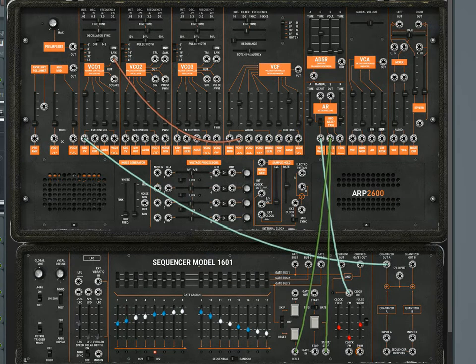We'll cover the use of the gate buses in greater detail later, but let's look at how to use gate bus 1 to control the frequency of the clock. At each step of the sequence, 1, 2, 3, 4, 5, 6, 7, 8, 9, 10, etc., one of the 3 gate buses can fire. And depending on how these switches are set, you can decide which gate bus will be fired at which step of the sequence. So this means that gate 1 will come on the first step of the sequence, and gate 2 will be on for the rest of the sequence.